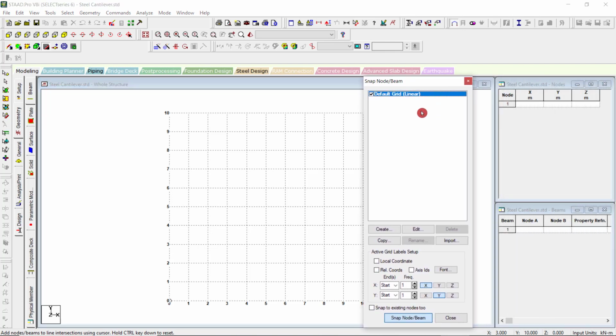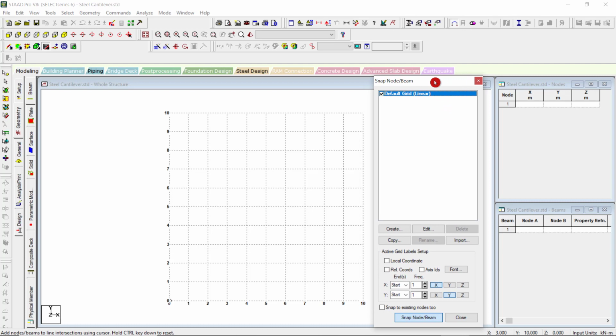This displays the table. We have the node source. So you can see the coordinates at the left bottom location. That is, x is in the horizontal, y is in the vertical, and z is the perpendicular direction. As this is a planar structure, this component is always 0. So you can directly give the node value here like 0, 0, 0 as the origin, and all the z components should be 0 for this case, being a planar structure.